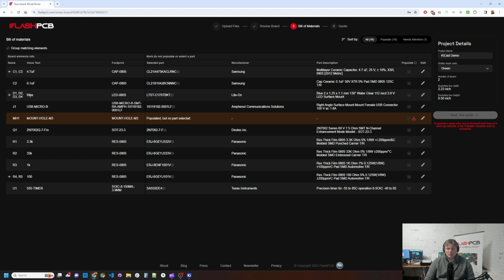So for instance, if you put blue, we understand that you're looking for the color of the LED. You could put BLU, we still understand that. You could put things like part numbers. So for instance, here we put a part number. For resistors, you don't even put a unit, but because it's a resistor, we know this is going to be the resistance of it. And we can see we selected the correct resistor that fits all of these.